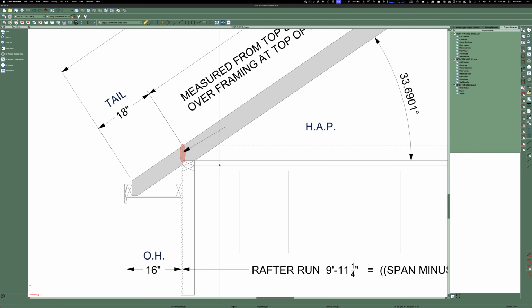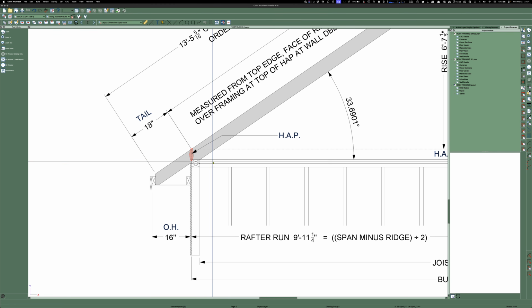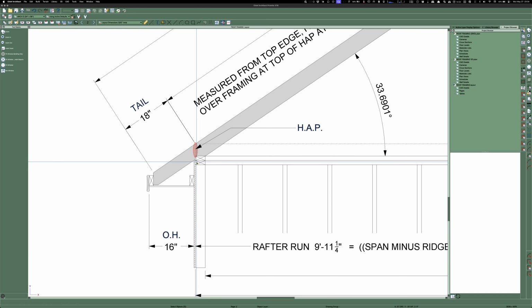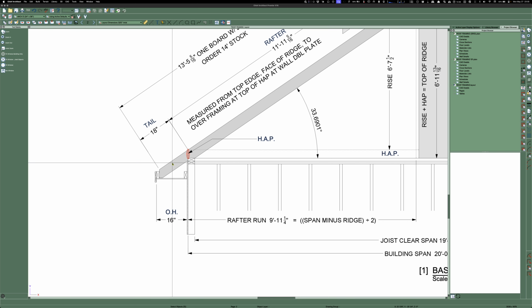So I am never going to give up the double plate, but I'm thinking I'm going to build all my outside plywooded walls, single plate on the bottom, stud, single plate on the top, square them, sheet them, stand them, and then use a nice straight 16-foot 2x to double plate everything. And I've seen that done before on the inside, where guys will just raise the single top plate, get the walls up, and then they'll come through and lace it all together. But